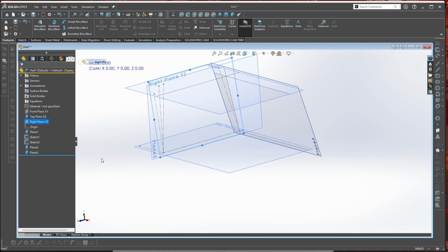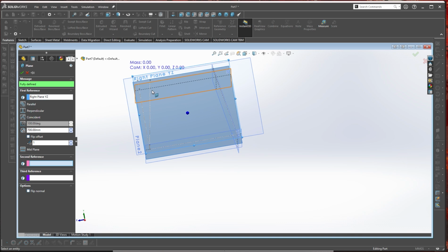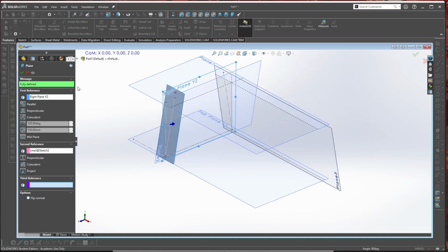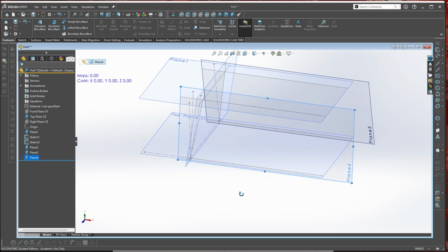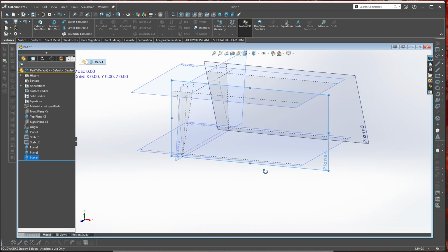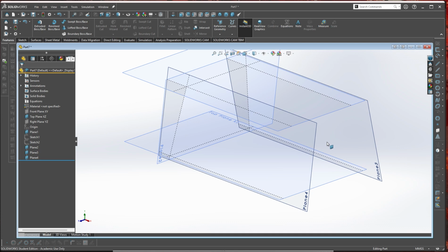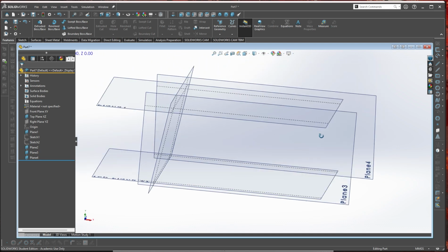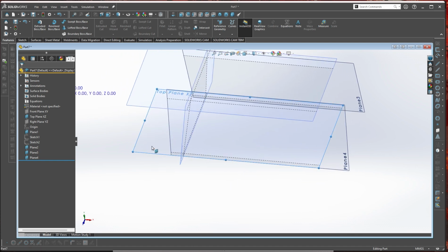We're going to select our right plane again. Select reference geometry. We're using this again as our coincident. And that should start looking sort of like the shape we created there, right? So we're creating like a box. By doing this, now we can take this sketch, make that invisible, and that sketch, make that invisible. So now all we have is a little box to put everything into. So in theory, we could do everything in one 3D sketch now.